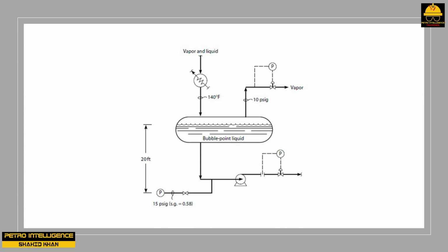sea level. Look up, on a vapor pressure chart, the vapor pressure of the liquid pumped, at the measured pump suction temperature, in psia. Multiply the difference between the two above pressures by 2.31 feet, for water. Divide by the specific gravity at flowing conditions of the liquid: 1.00 for water, 0.85 for diesel, 0.50 for propane at the pump suction temperature. Note that the pump suction pressure is the pressure downstream of the pump suction screen, and not a pressure read from a control panel screen. When the required NPSH of a pump equals the NPSH available to the pump, it will cavitate or slip.